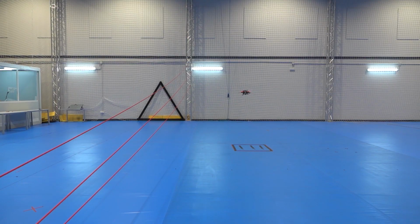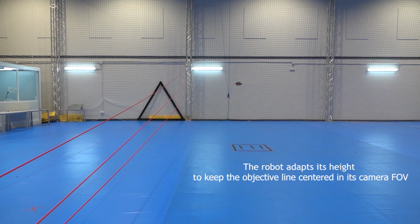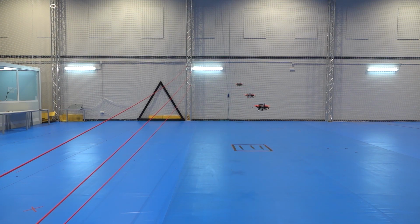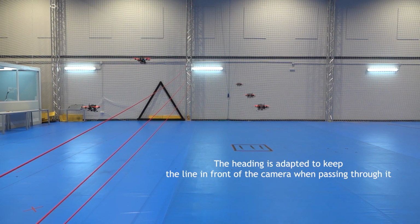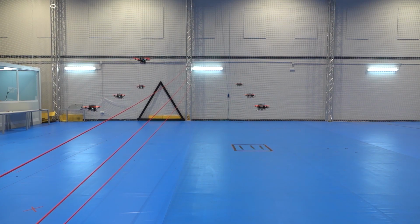We analyze the performance of the system in two different sets of experiments. First, we test the proposed mathematical modeling without using the perching trajectory generator. The modeling is tested inside an onboard nonlinear model predictive controller that is used to perform inspection flights near a set of power lines. The quadrotor follows a simple waypoint-based trajectory and adapts its height and yaw angle to keep the middle power line centered in its field of view, while also avoiding two potential collisions with them.